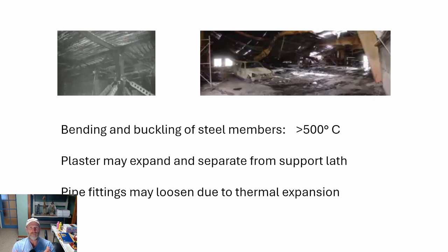So that's roughly 50 times more than, let's say, concrete. And to put that in perspective, copper is like 360. It's just monstrously higher. So copper very rapidly follows the smoke layer. But in the case of steel, it's going to follow the temperature of the hot gas layer around it. But there's some caveats to that you need to understand.